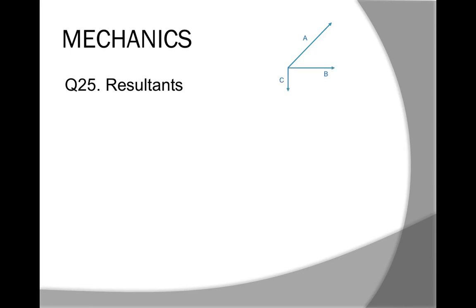I'm just going to show you that animation again. We want to take those three forces, and we can add them tip to tail. If we do that, we can then find our resultant by breaking up our components and finding our missing part. If we go from start to finish, we can use our components to find our resultant. Ultimately the shape needs to close. The resultant will be the shape that's needed to make it close.